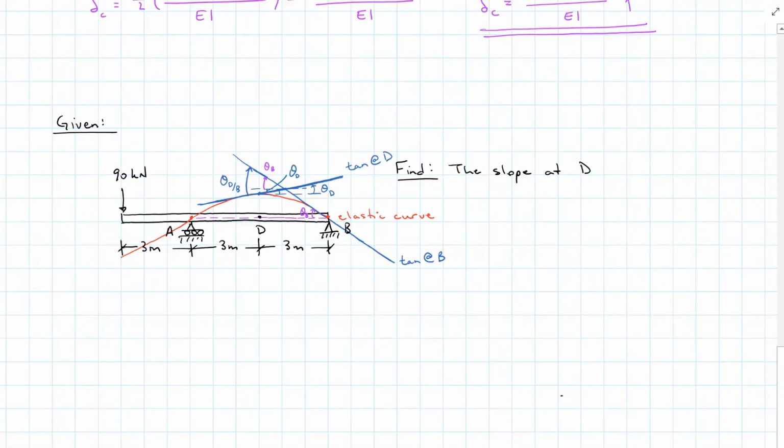Let's zoom back out so we can get a good look at our picture. So right triangle, and extend that tangent line up. Just like we did the last example, we can find, in this case, TA with respect to B, point A with respect to a tangent line drawn at B.